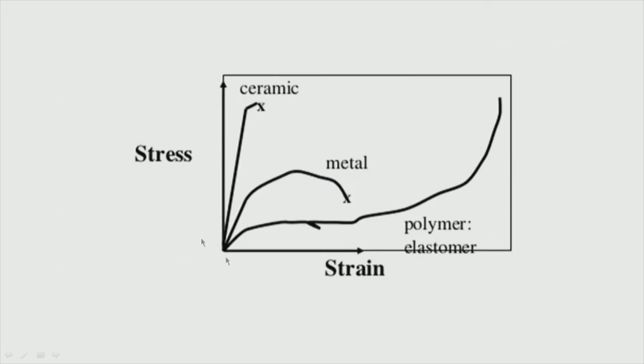In this picture, if you see the stress strain diagram, for metal you will have the elastic region, then the plastic region. Polymer, as you can see, it can go like this. Ceramics will have a high modulus, but very high crack propagation. So, it is not tough, so it does not take tension. It cannot be used in such applications, it will just snap here. You do not see a plastic region at all, unlike metals. That is the stress strain diagram.